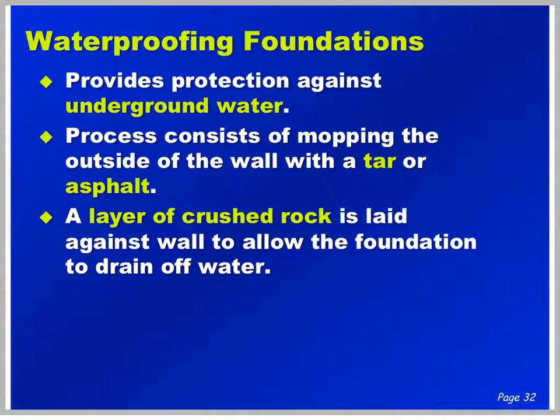Almost all foundations will need to be waterproofed to eliminate the intrusion of water from below grade. Typically, there will be a barrier like tar and, or in more advanced systems, a layer of drainable gravel around the structure. Some concrete materials can include a hydrophobic admixture that protects the concrete from water intrusion.